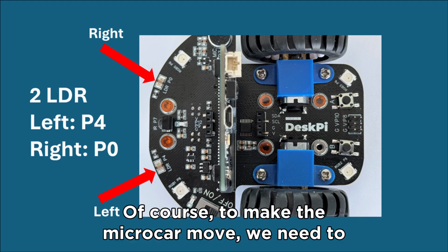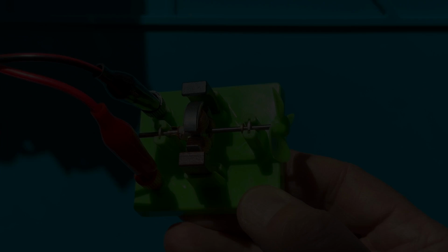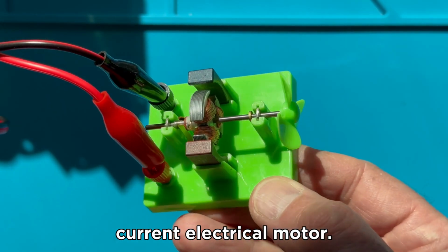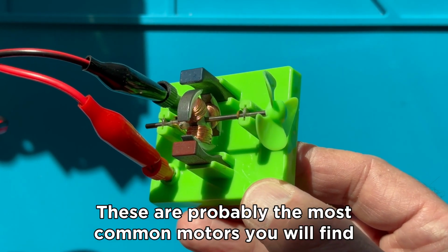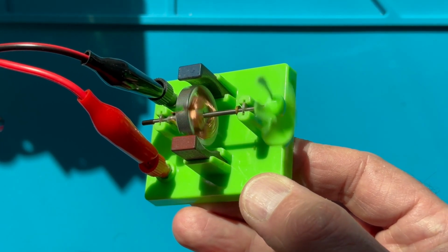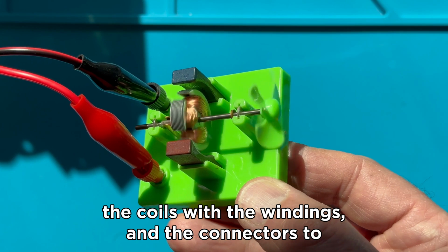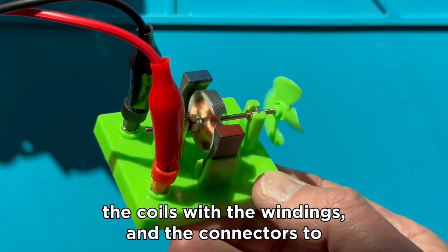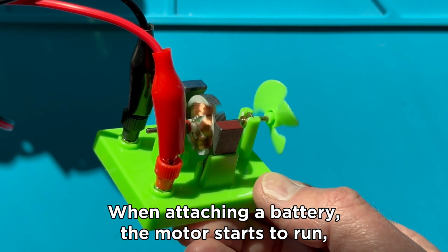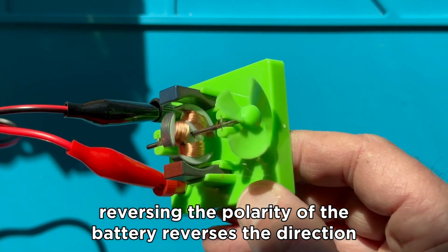Of course, to make the microcar move, we need to activate the motors. Let's first take a quick look at the inside of a direct current electrical motor. These are probably the most common motors you will find in cars, cycles, fans, and so on. This model shows the inside, the permanent magnets, the coils with the windings, and the connectors to the power source. When attaching a battery, the motor starts to run. Reversing the polarity of the battery reverses the direction of the motor.